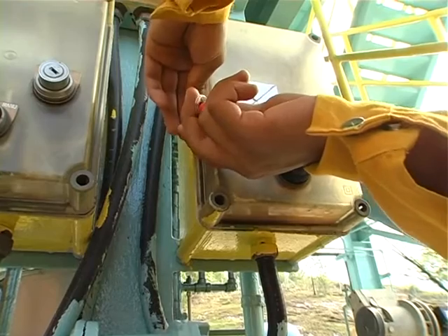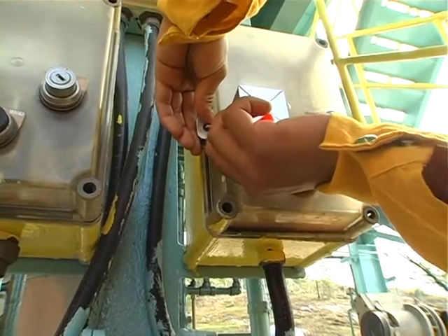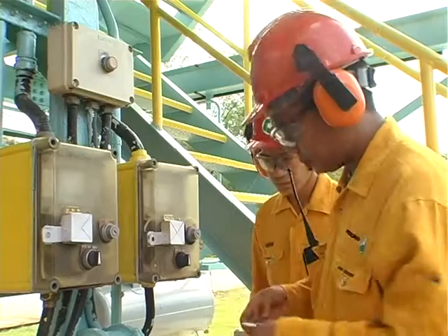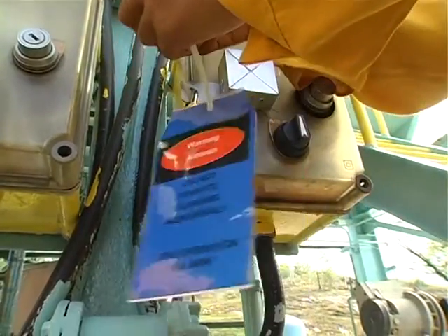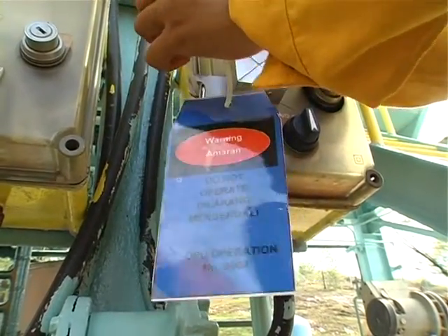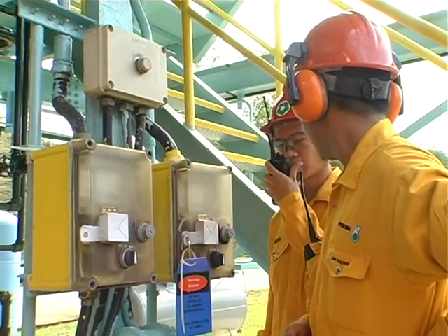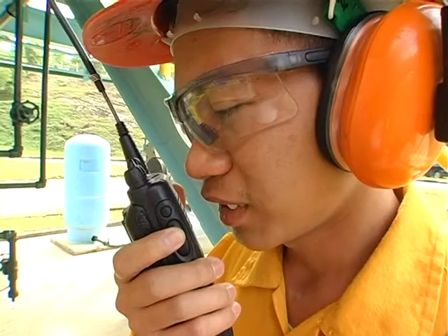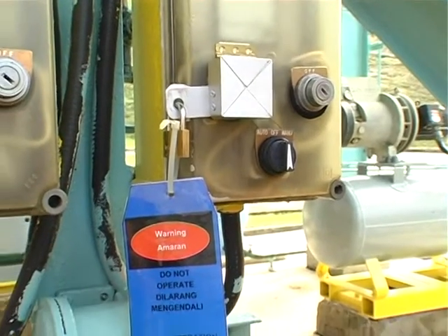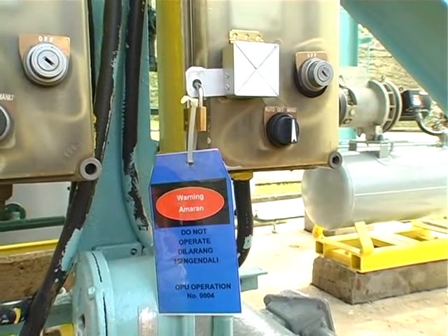The AAR must place a group lock wherever possible, followed by the Operation Blue Tag on the correct field start-stop switch. The clear and try steps must be witnessed by the AA or another AAR to confirm the status of the electrical isolation.